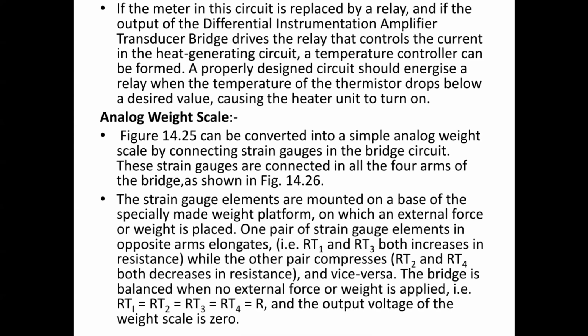If the meter in the circuit we referred to is replaced by a relay, then, since the meter showed the amount of deflection for a change in the physical quantity, here, if the temperature changes, the thermistor resistance changes and the meter shows the deflection, that is the change of temperature. If you replace that meter with a relay, the amplifier drives the relay that controls the current in the heat generating circuit, and a temperature controller can be formed.